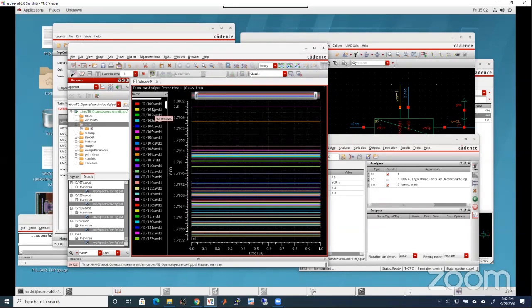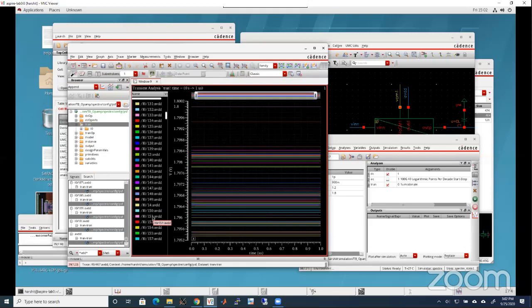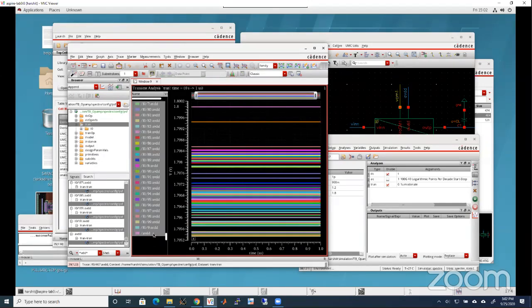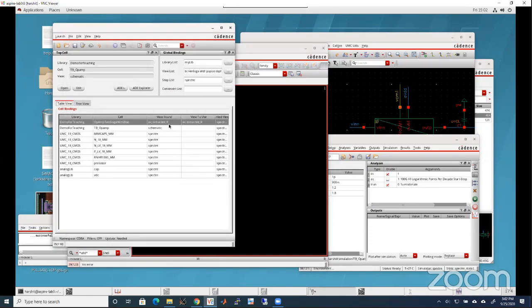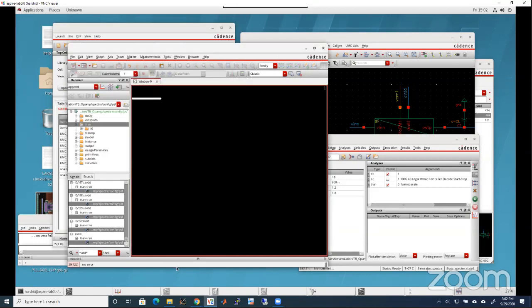So now we can only select the resistor and we can see the drop. I am selecting the resistor only netlist. Okay, R extracted netlist. You can see that AB extracted R netlist. I am not doing the RC extracted, because why should I simulate an RC extracted netlist which is much bigger than an R extracted netlist? You got my point, right? So that is why we'll see the VSS also. How is the power drop in the VSS?